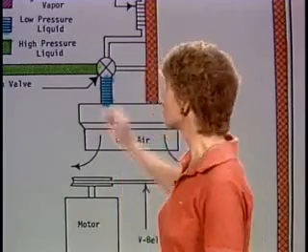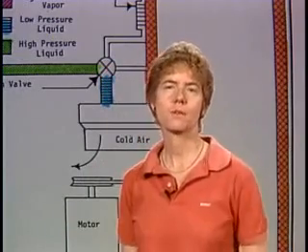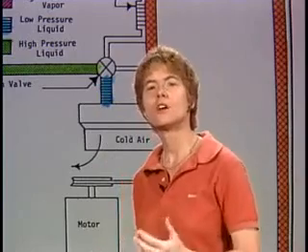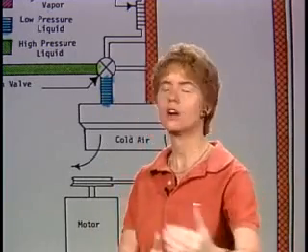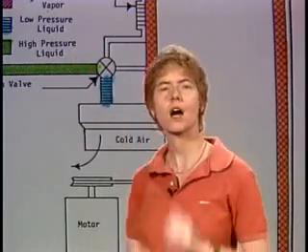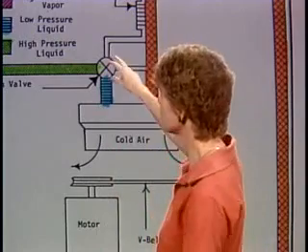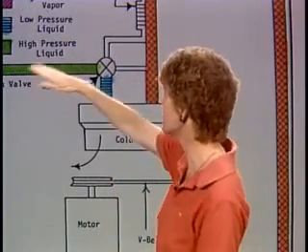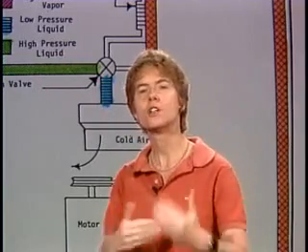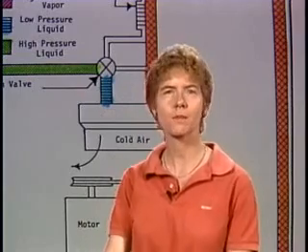Now, the expansion valve is the second place where water is very, very likely to freeze in a Freon vapor cycle cooling system. So if the vapor cycle cooling system will not take a charge, you're trying to recharge it with Freon and it will not take a charge, the most likely thing that's at fault is the expansion valve, that water has frozen in the expansion valve and is not allowing Freon to go in and through the system, because it's very easy for it to plug up there.